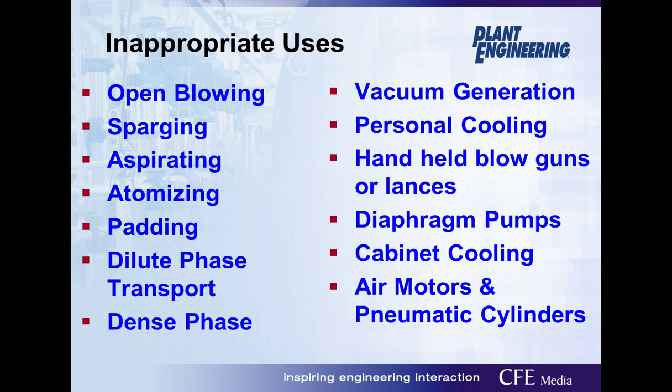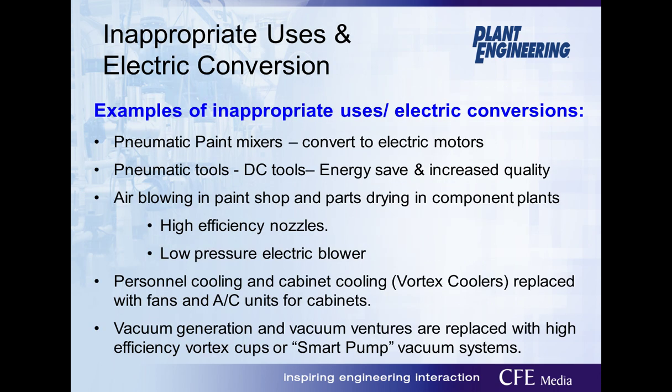Because again, back to that previous slide, if I'm doing some mixing, for example, with an air motor, why can't I use electric? Some of the examples of these that I have done in my career when I was at Ford is changing pneumatic mixers over to electric motors in the paint shops. Now, you may have to use explosion-proof motors, but it is something that can be done.